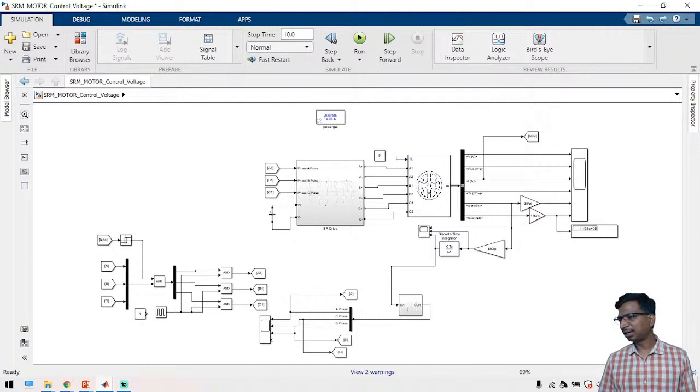When the first phase is off, then the second phase is on. But how will the diodes in the first phase dissipate the inductor energy? That will not be available for the entire period. It is only for a very small fraction of a second.